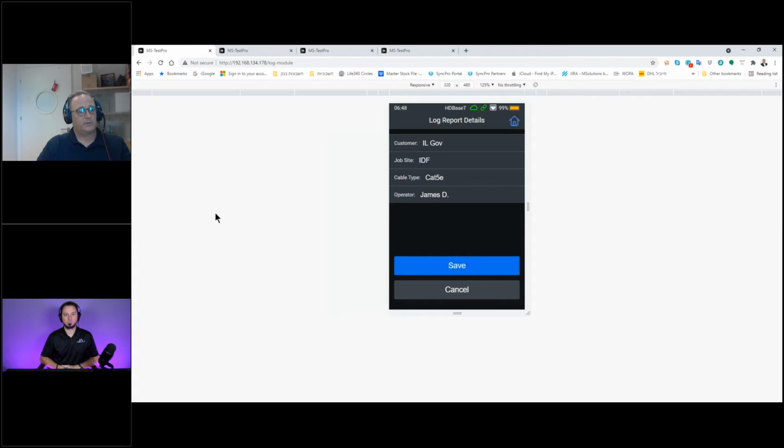We've seen also problems that happen because of different sources that are running for a long time. From time to time, they have a glitch on the HDMI interface that drops from 4K to full HD. This can be for a second, because it was having a firmware update, or a certain operation was done there, and you cannot capture that. With those log files, we are catching those 70 parameters twice or three times during 1 second.